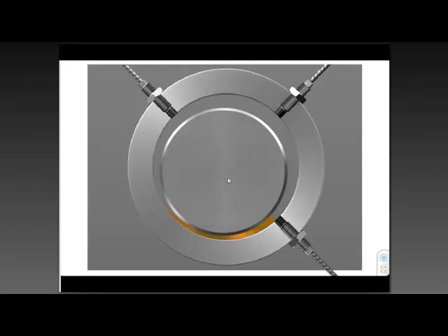We have this little pillow of oil that's set up, this little oil wedge. So any motion that we see due to unbalance or any sort of problem, the motion is deadened because it doesn't transmit through the oil to the housing. It's not as sensitive if we just measure from the housing.